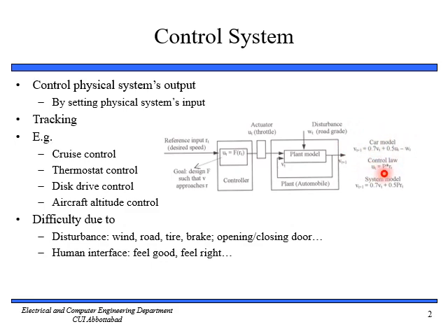So what we are doing is multiplying by this control law. Here you can see u of t is equal to p into r of t. We have to find some value of p such that we can control this v of t. This r of t is our input, and p is proportional, simple as in the case of PID.